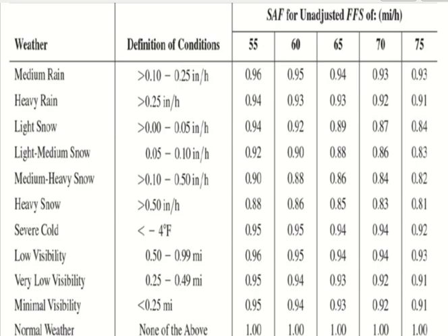Now what will happen if you are out of the range? This is true for all the tables, not only this one. When you are out of the range, we will pick the last value. Clear? So the last value is 0.96. So this is my speed adjustment factor. Clear? So the final speed will be this multiplied by this. So how much is this now? The adjusted speed is 50.6.